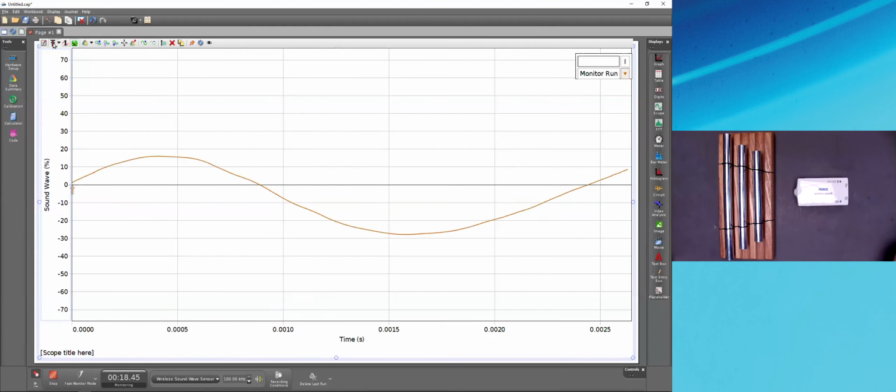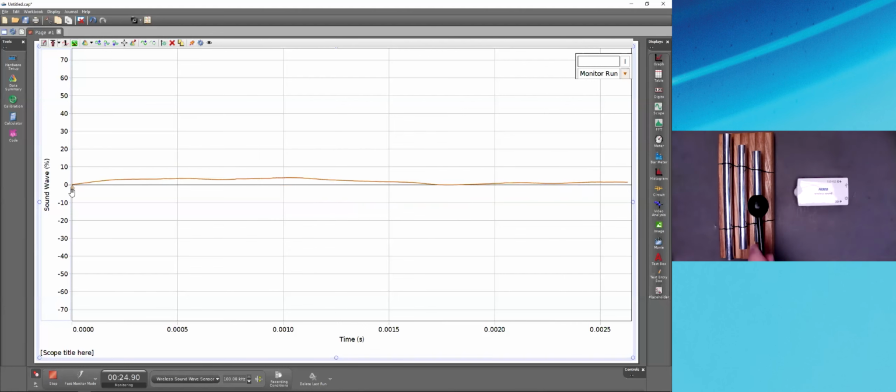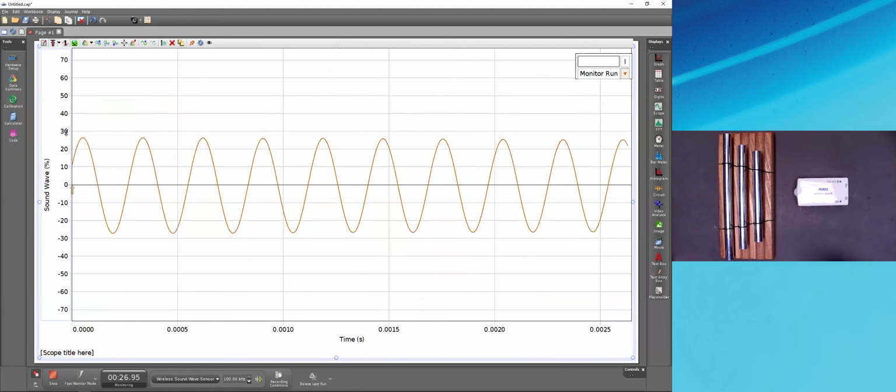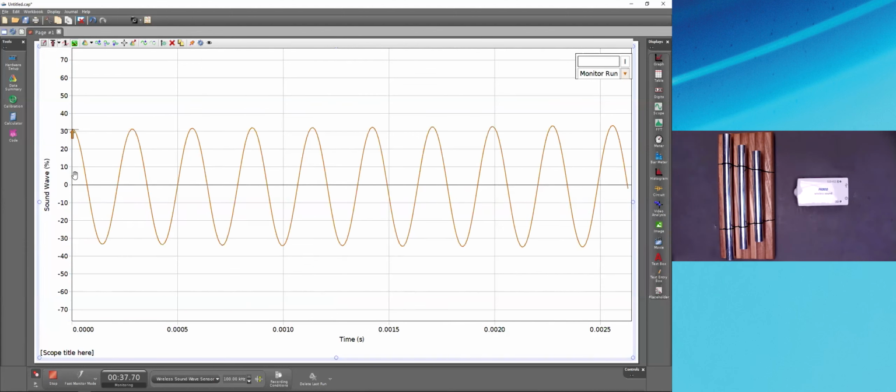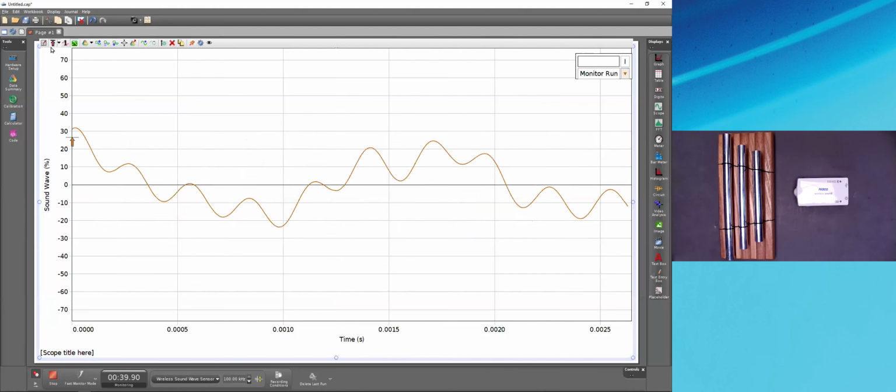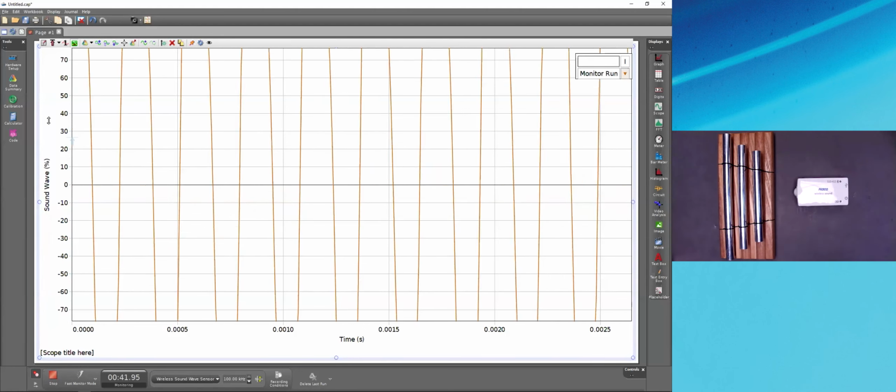We do have a tool here that allows us to turn on a trigger though. So now it's only triggering at a rising above 0. And now if I hit the chime, you'll see that it doesn't jump left and right as much because it is always starting the trace at a particular point. We can adjust the level of this, essentially using it like a trigger to capture something, or we can turn off that and it will start whenever, as fast as it can.